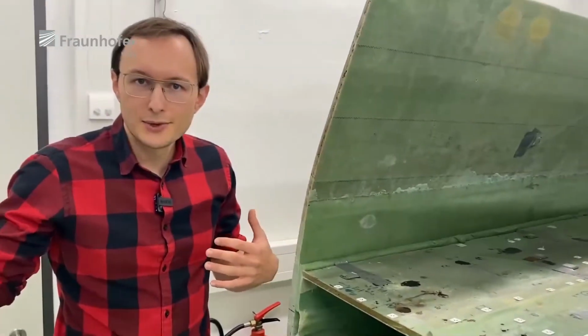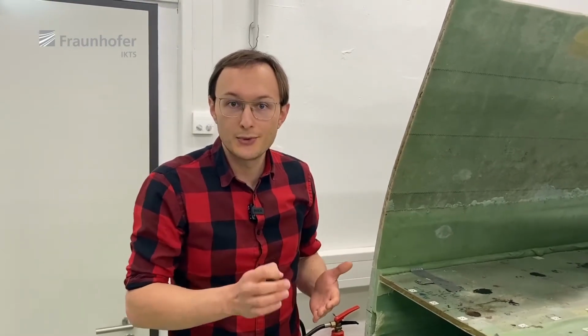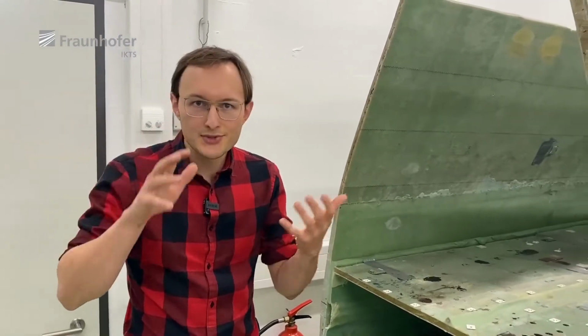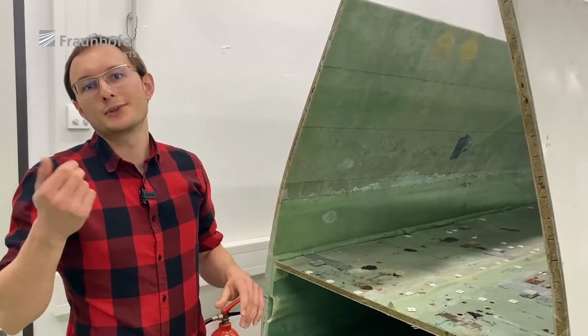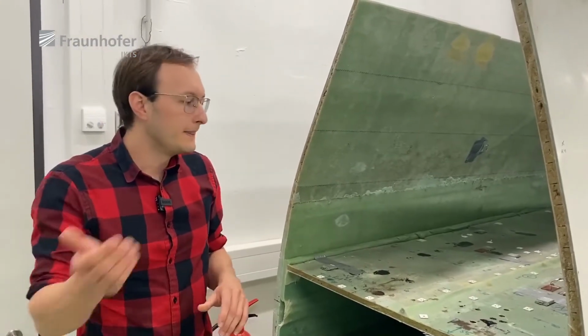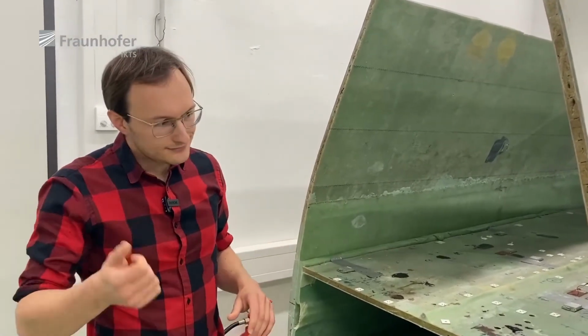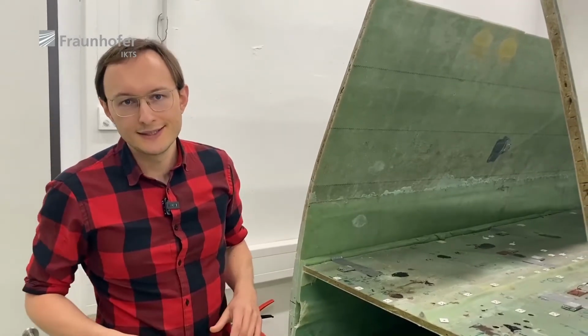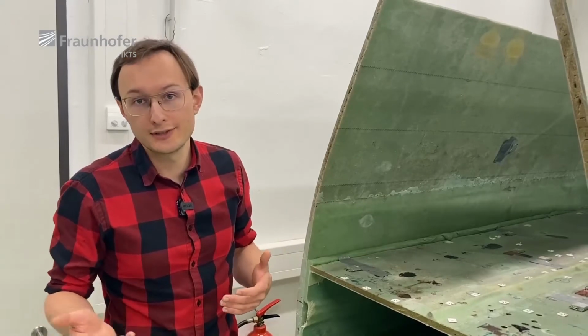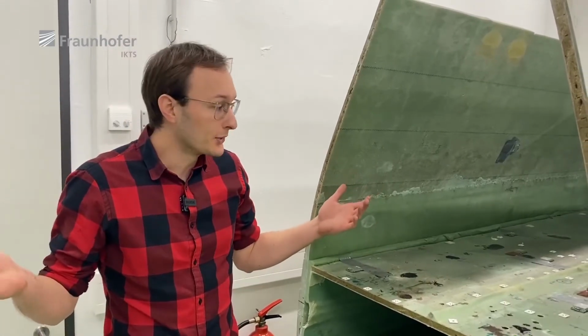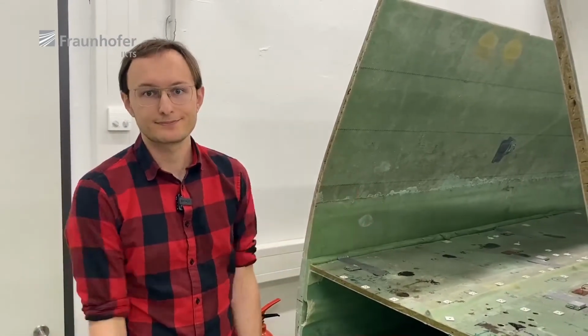By taking the runtimes of those cracks into consideration, we can extrapolate the position of the cracks, and once the number of crack and noise events at the same location exceeds a certain threshold, we can raise an alarm flag to the operator of the structure, so he sends someone to investigate before, well, the turbine stops working or worse, something breaks, which could be dangerous.